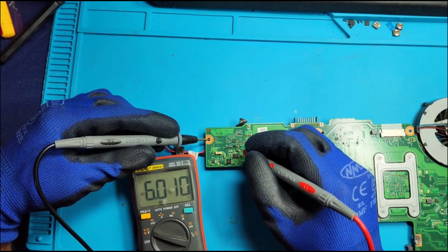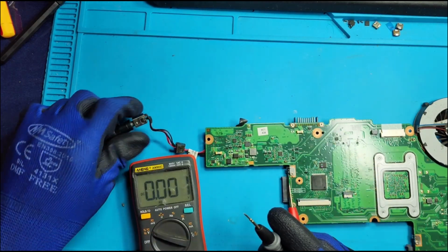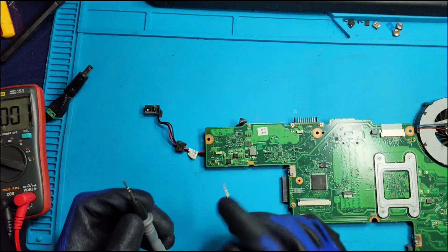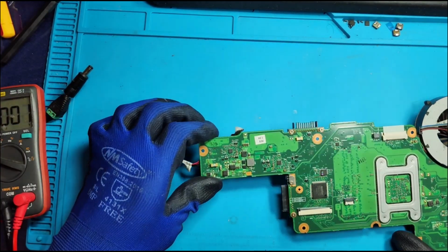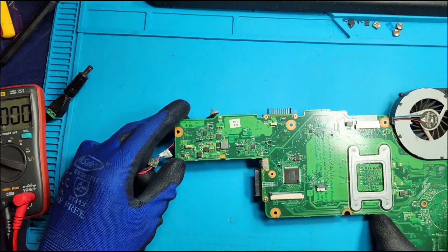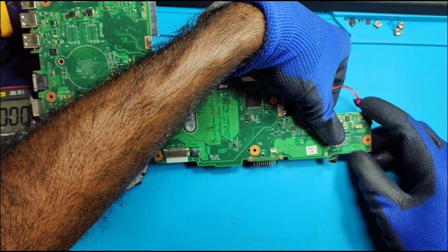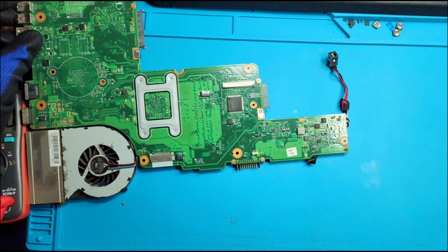Okay. So now we need to confirm why the charger IC is not producing the AC drive voltage for these two MOSFETs. For that we need to understand the working principle of the charger IC here. So we can go to the data sheet of the charger IC and have a look at it and then come back.